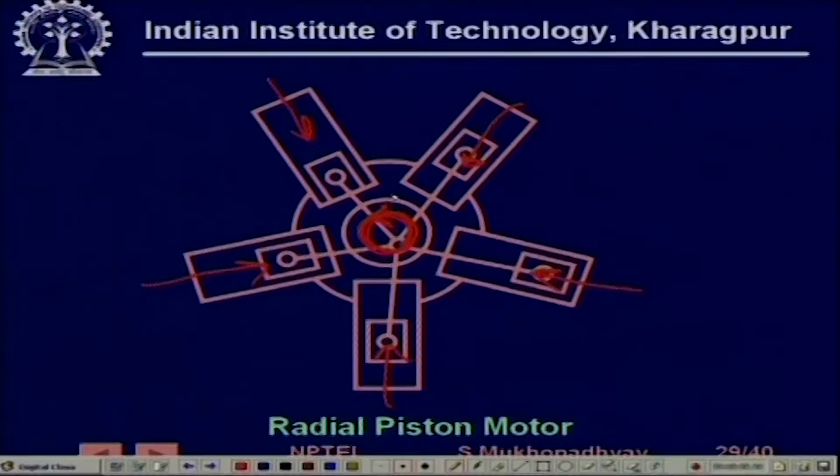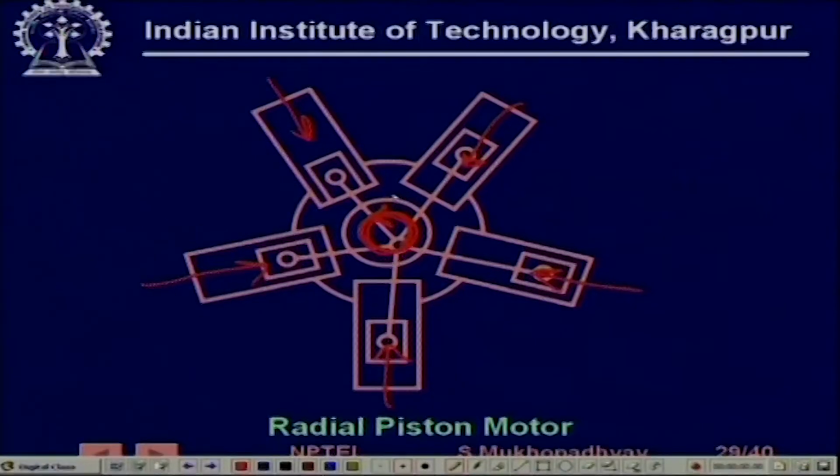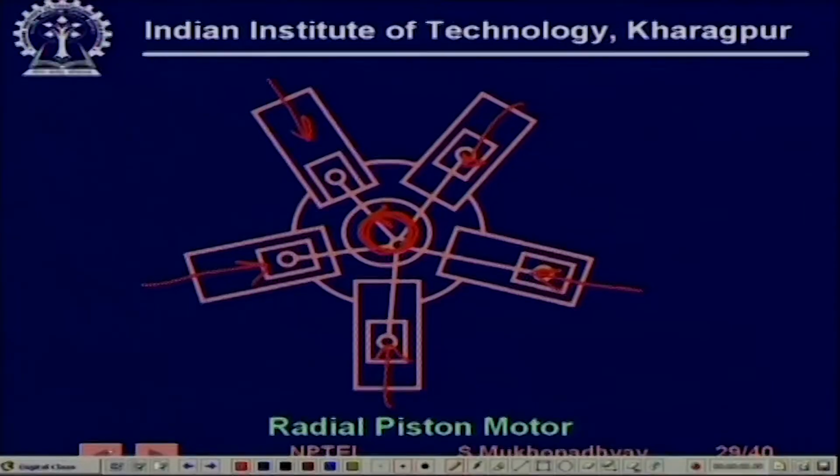So this is of a positive displacement type, that is, in every cycle of the piston movement a certain amount of air goes through the system. Similarly, you can have non-positive displacement type. Here we have not shown a figure, but it is exactly similar to the vane motor of hydraulic systems in principle, although there may be constructional differences in design.